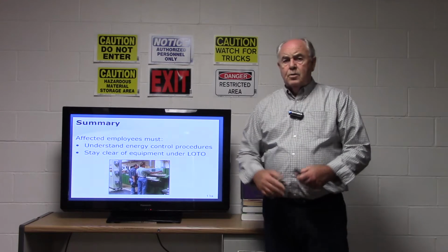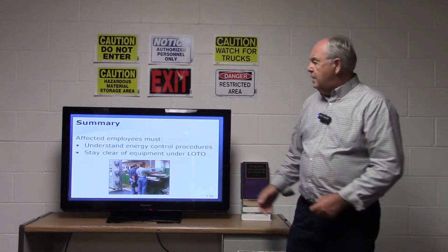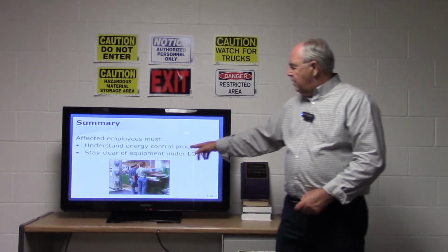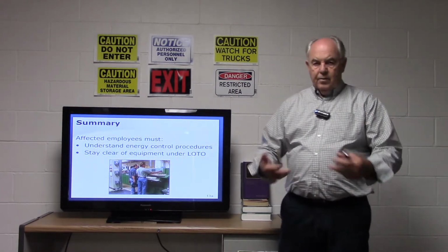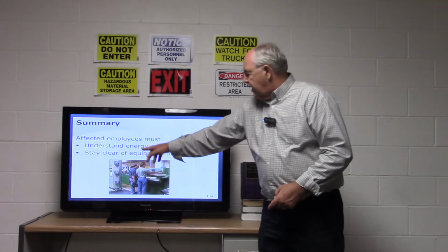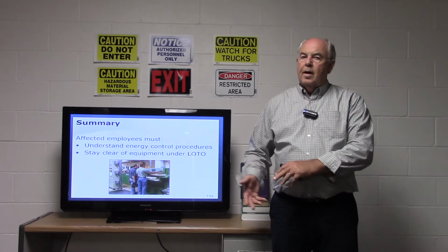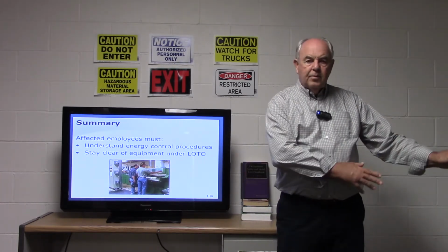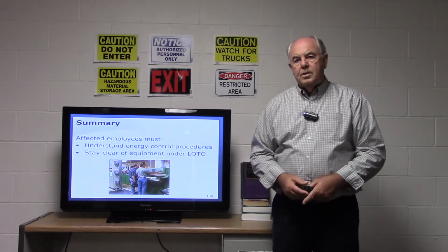Now keep in mind, as we summarize lockout tagout training for affected employees, that affected employees must understand the energy control procedures. That's what we've been talking about throughout this training video. Stay clear of the equipment while it's under lockout tagout. Remember, you're not authorized, you're affected. You have to move away, and you can't help an authorized person work on a piece of equipment.